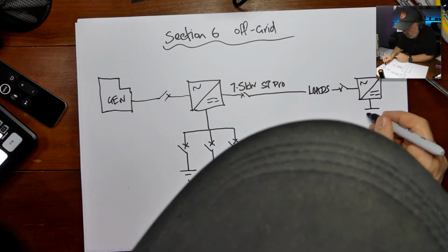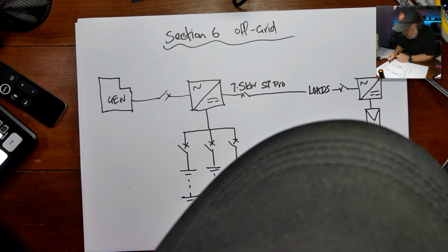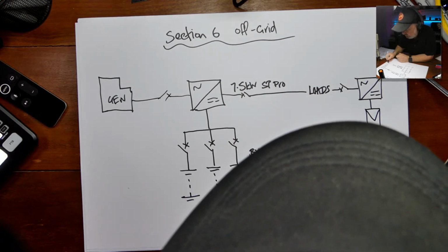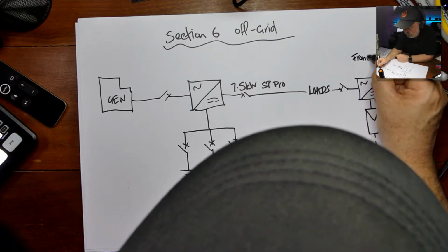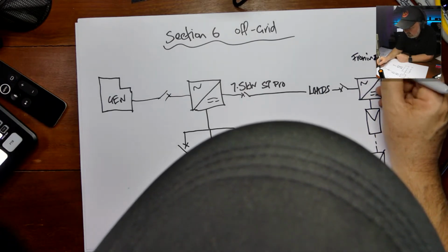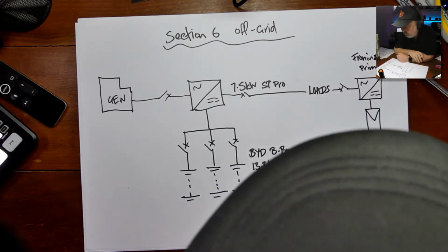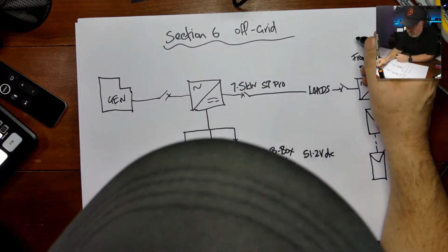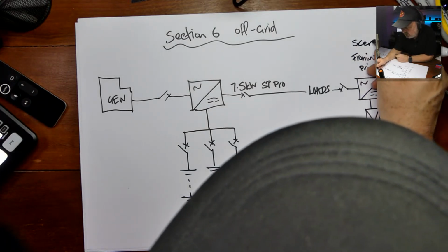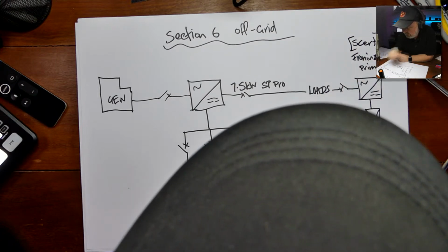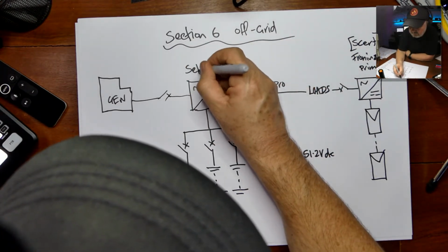And it's got its solar array connected to it. So it's actually connected on the load side of this SP Pro. So this here is a Fronius. We're putting in a Fronius 8.2 Primo. So it's an 8.2 kilowatt Primo, but rather importantly, it's what's known as a Selectronic certified, S-Cert for short. And this is the SP Pro, the Selectronic battery inverter here.